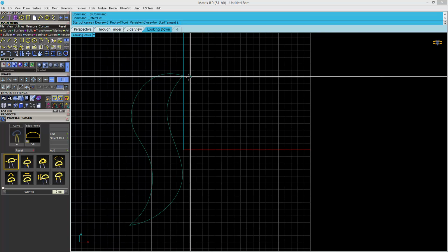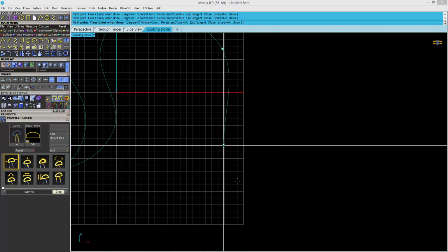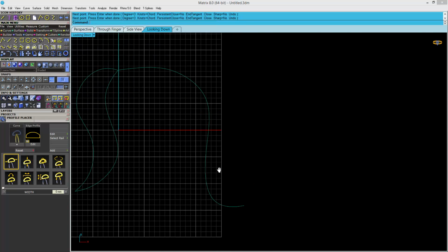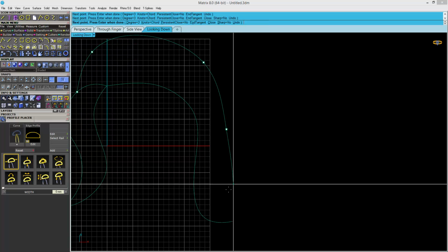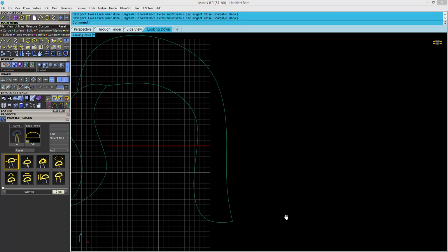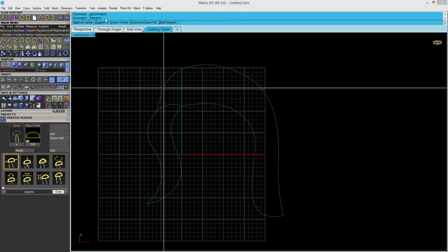So using this you can start to just draw anything for the moment, get used to it. When I want to stop, I right click. Imagine if I need to stop here, for example. Then if you want to continue, right click again, anywhere, doesn't matter. Then it will appear. The main thing you need to understand is that right click means the last command you used. So if you want the last command, you just right click and it will open up the interpolate curve again.